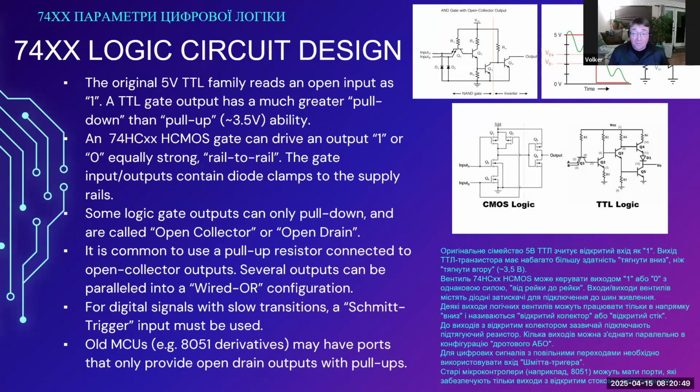As part of the development of the digital logic, a maximum rise and fall time was defined for signals, and the outputs of digital logic were guaranteed to stay within the limits of this rise and fall time. It had to be faster than roughly 40 to 50 nanoseconds to work properly.